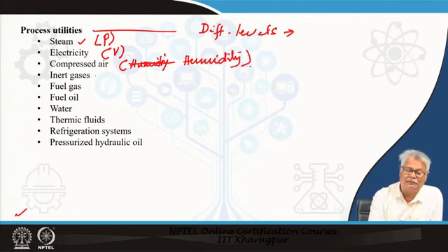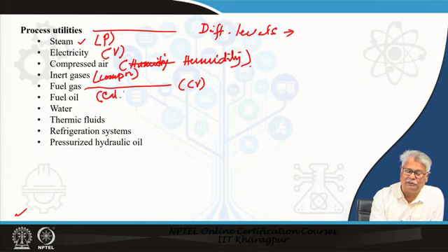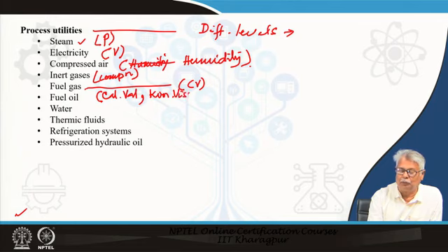And then naturally you have inert gas. In case of inert gas, what is important is basically the composition. In case of fuel gas, it is again the calorific value, which naturally is of importance. The same thing is in case of fuel oil also, that means the calorific value is important, but at the same time the kinematic viscosity is also important. We will know why it is important in case of fuel oil.